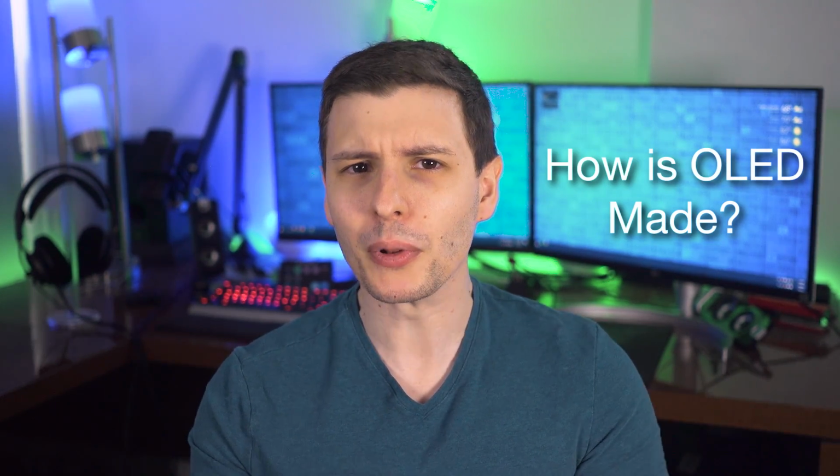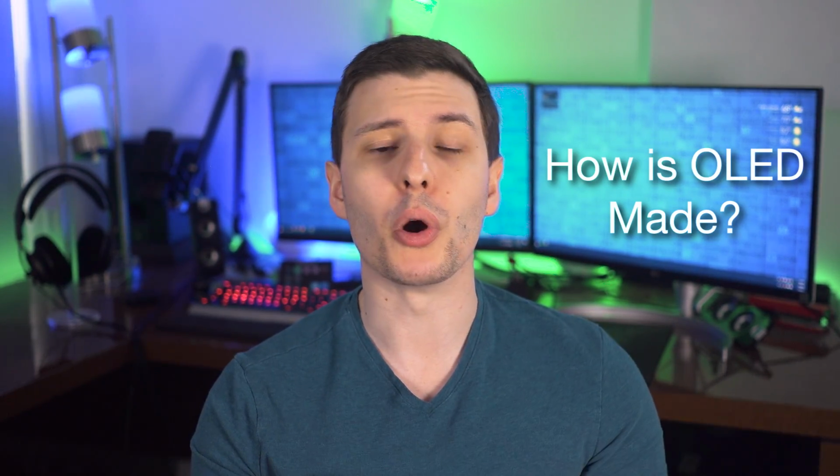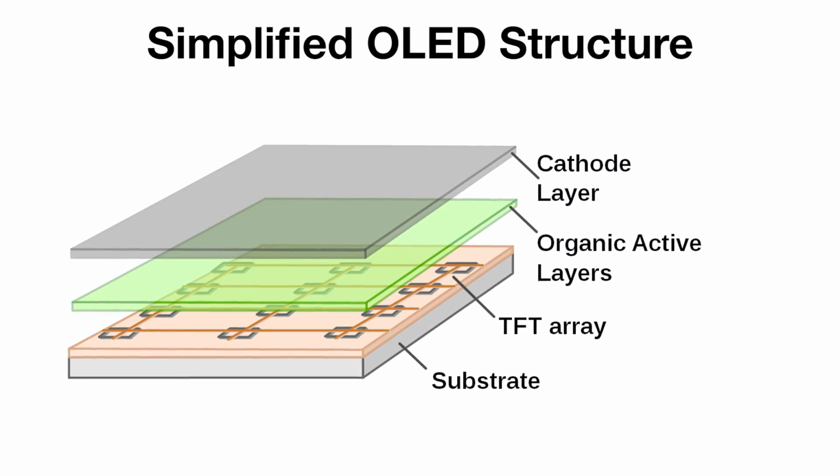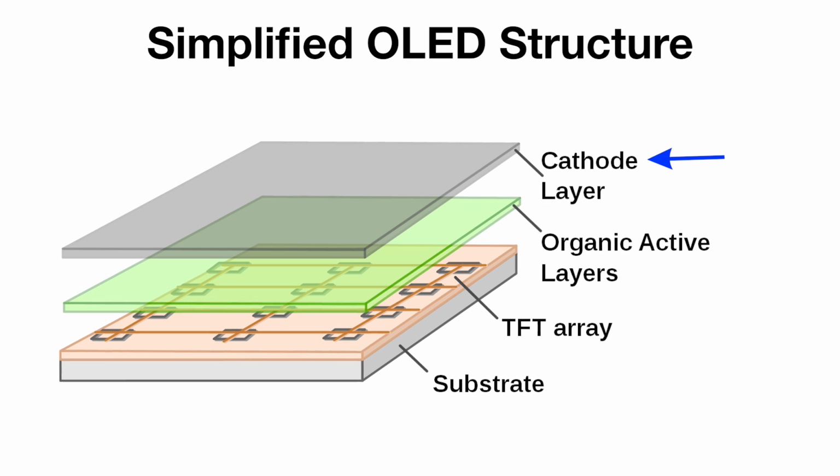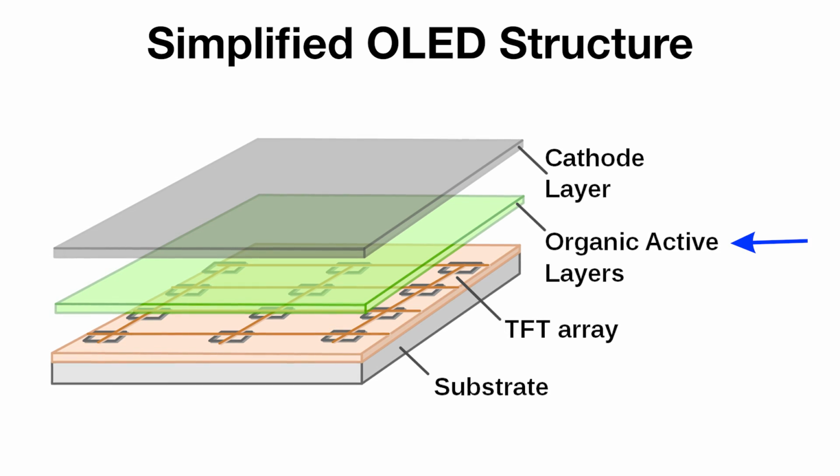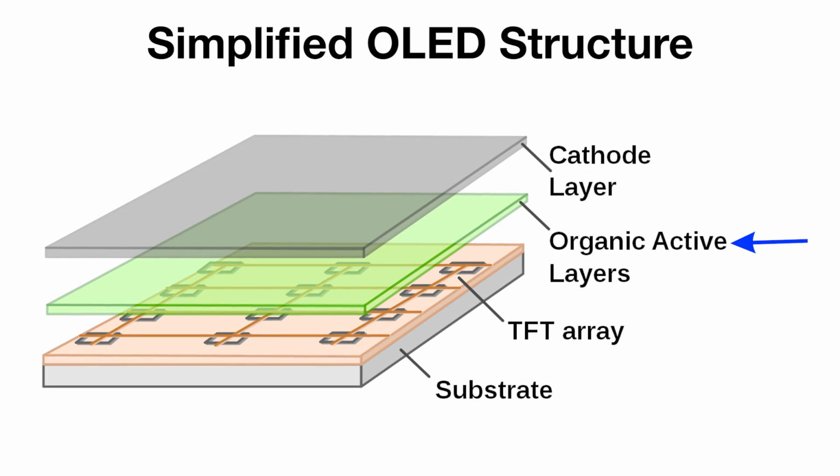So what is it about how OLEDs are manufactured that make them able to overcome this issue? Well, OLEDs are manufactured completely differently than regular LEDs. In fact, OLED pixels aren't really made of a physical diode with wires and stuff at all. You see, with an LED, you have to cut from a wafer, like I said, and wire it up to pass current through it. Organic molecules, from my understanding, are a lot easier to manipulate though, so instead of using wires to pass current through them, you can just take one conductive sheet, spray OLED molecules onto it, and then sandwich it between another conductive sheet.